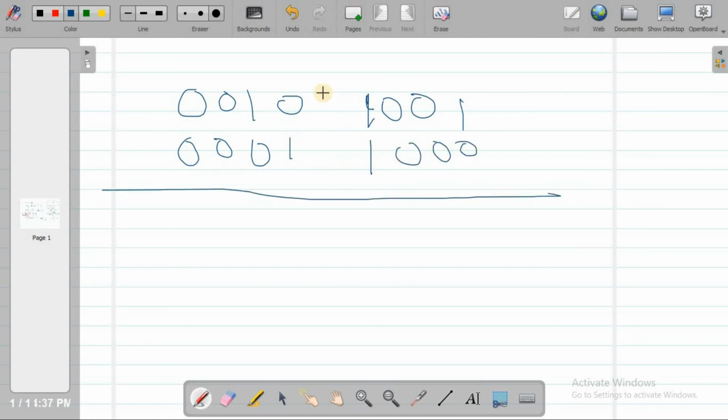So when you add, remember we have two nibbles, this side and this side. If you have a carry here, a 1 from the lower nibble, then the result here is not a BCD number. You must add 6 to correct the mistake.